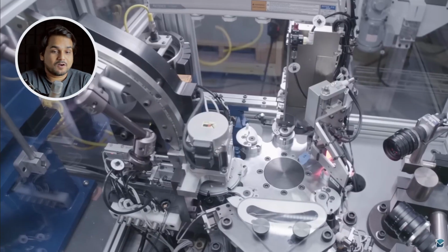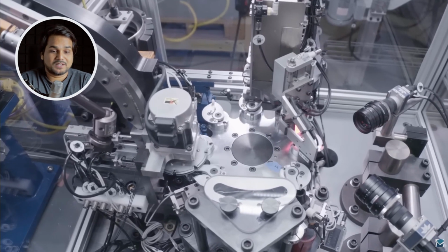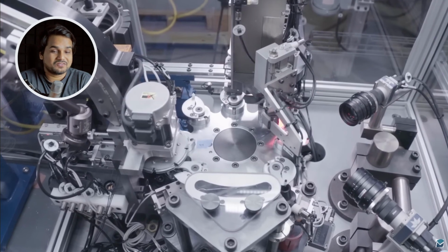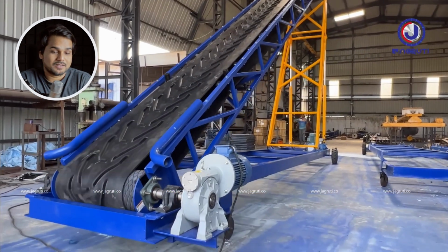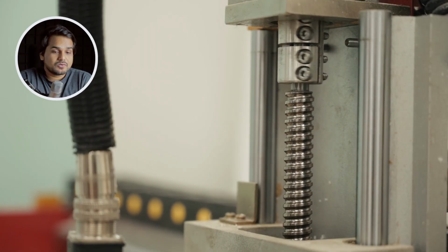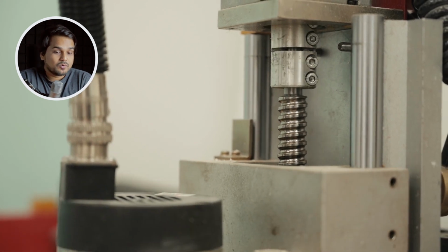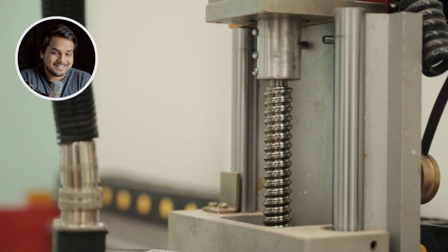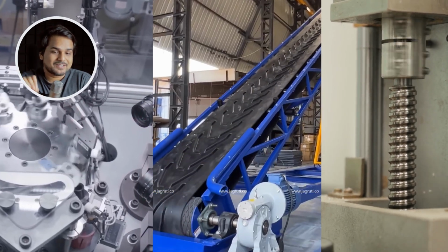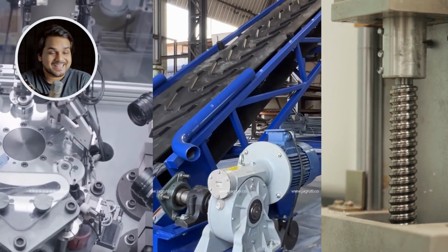Moreover, this is not a surprising or unique case. As mechanical design engineers, we encounter such cases very often. We often design indexing tables for assembly lines, where we rotate a disc plate around its axis very precisely. Also conveyor rollers, where cylindrical rollers rotate around their central axis. Also in ball screw or lead screw, we rotate the screw around its axis. And in all these cases, we must calculate the required torque to size the motor correctly.